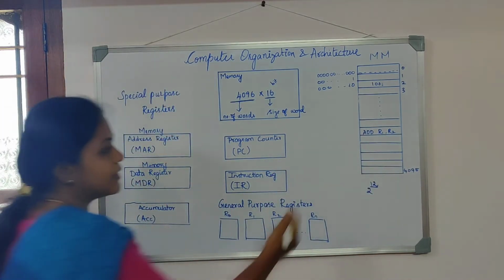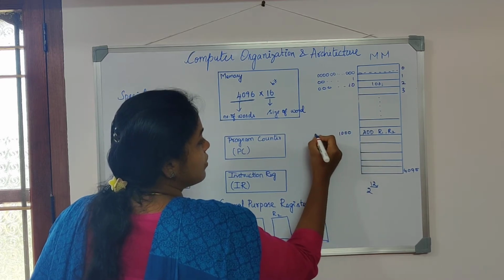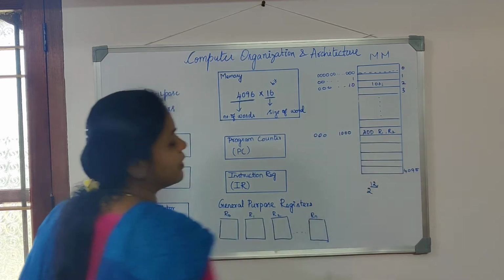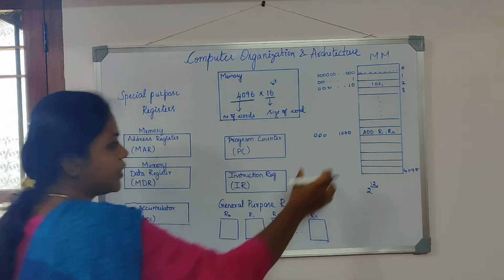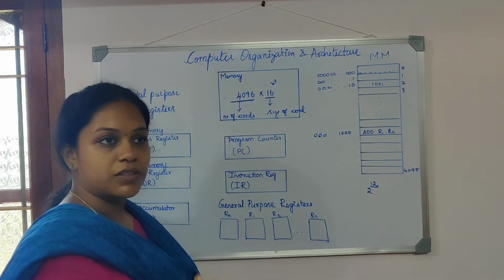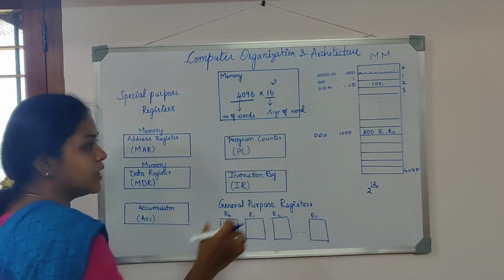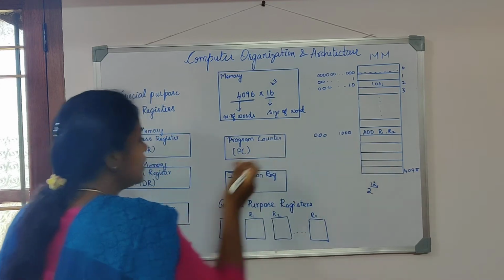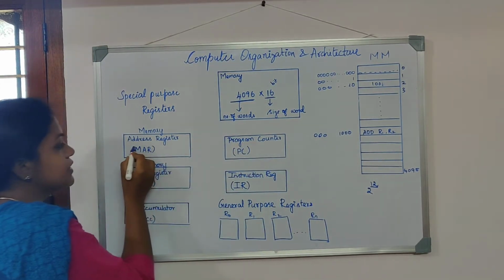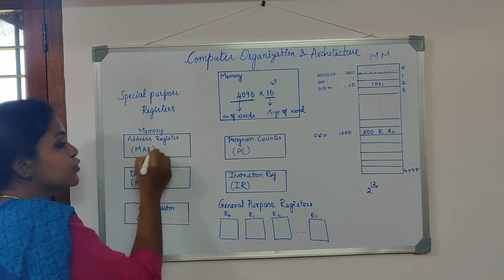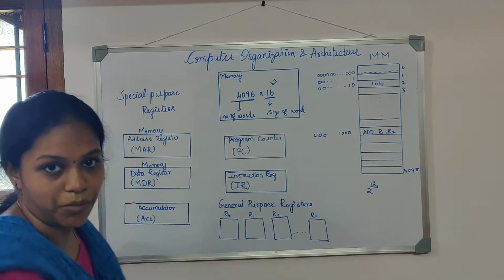There will be an address for this, for example 1000, 12 bits long, 0011 1110 1000 or so, is the address for this instruction. Now if a processor wants to fetch the instruction from this address, it will use the memory address register to store the address and to pick the instruction from the main memory.